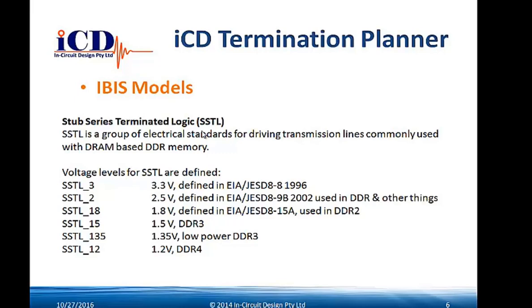SSTL_3 is actually 3.3 volt operation. A 2 is a 2.5 volt, 1.8 is 1.8 volts, and so on. So we have all these different models which can be used for just your standard SDRAM or your DDR4, for instance, and also low power devices.